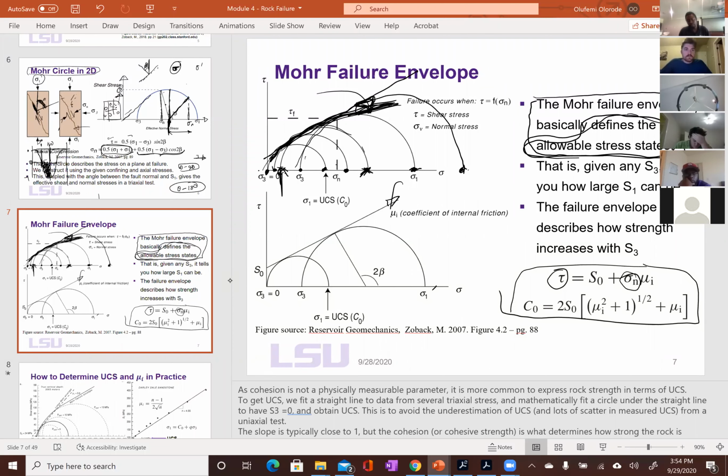And I'd explained, well, if you use the modified Hoek-Brown failure criteria, then it can capture that, but where does it get the parameters of that curve? It's totally empirical. And you don't have as many core samples from the top to the formation of interest, so it's not really a wise idea. So instead of all of those, we just use correlations based on well logs. We still tend to use this linear stuff when we have core samples, but we rely on UCS estimated from well logs for formations above the formation of interest where you have no core whatsoever.